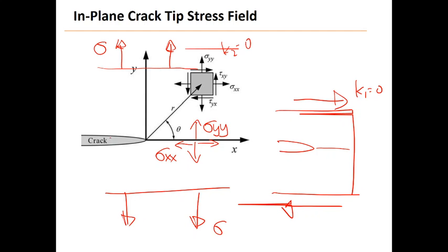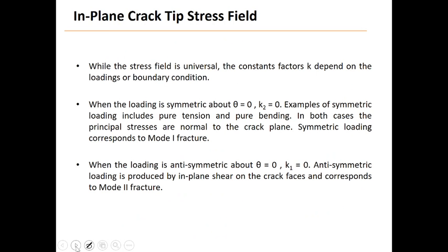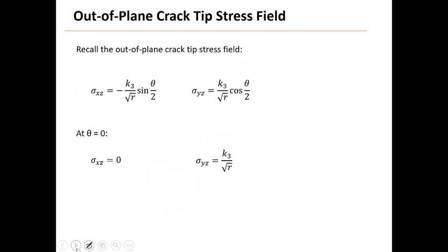You can just hang an extensometer around the mouth of the crack, and then you measure. And since you have the displacement solution around the crack tip, you just have to set theta to be 90 degrees, 180 degrees, and the solution will give you the displacement here. And people did go measure that displacement behind the crack tip and compare with the solutions. So these are ways to make sure your solution is correct.